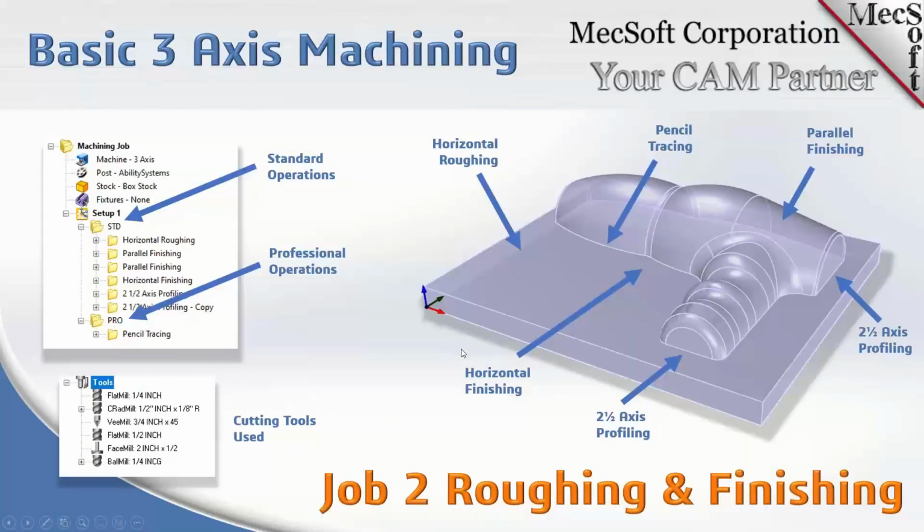And for this part, again, the machining job over here on the left, we've got a horizontal roughing, two parallel finishings and a horizontal finishing to finish the boss portion of the hair dryer. It's a hair dryer mold. And we've got some profiling, and then we have the pro. We have a pencil trace for the pro. But I'm going to show you a good way to pencil trace without using the pro. For this part, it worked out pretty well, and I'll show you how to do that. And then the tools are down here at the bottom.